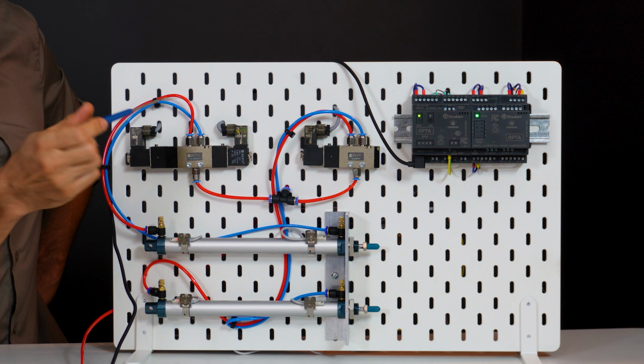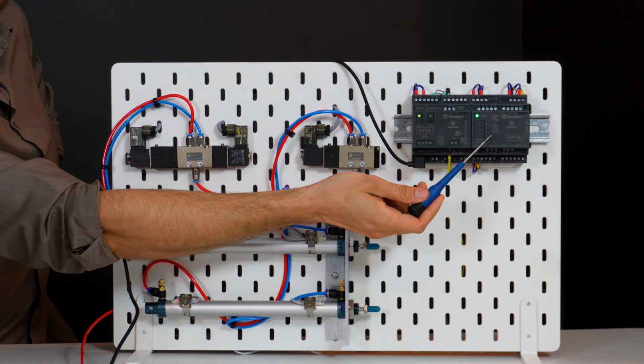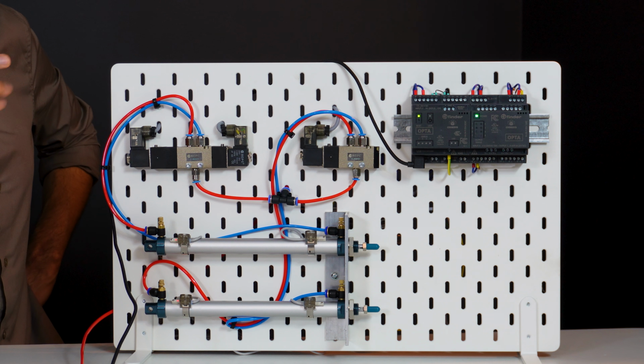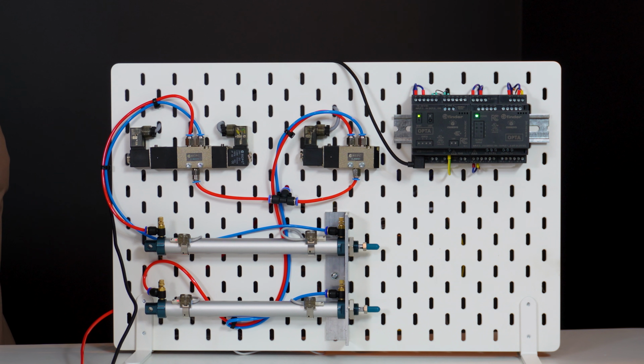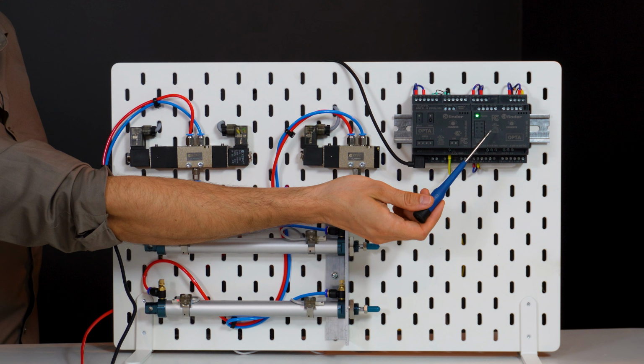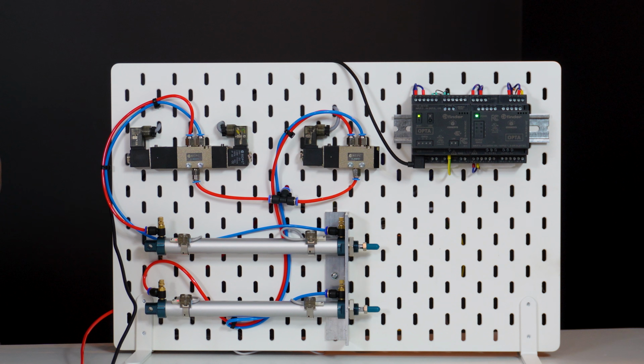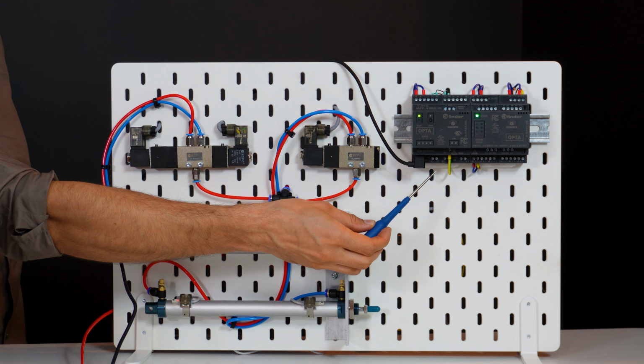The key in this application is the use of an expansion module for the Finder OPTA controller equipped with SSR outputs, which are transistor outputs with a load capacity of up to 3 amperes. With such an SSR module, we can very dynamically control pneumatic systems and coils in hydraulic solenoid valves, which draw much higher current, even up to 3 amperes for a voltage of 24 volts. If you want to control coils with higher voltage, for example, 230 volts, you can use relay outputs.